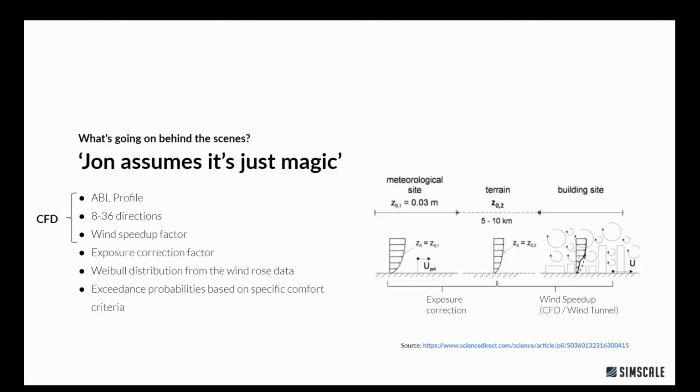In the end, what we're interested in is getting a quantitative measure at the local place where people sit, stand, walk, of how comfortable they will feel over a whole year, right? And this depends on the wind frequencies and the wind speeds locally, but usually we don't know what the speeds are locally at pedestrian level, in the middle of a city.